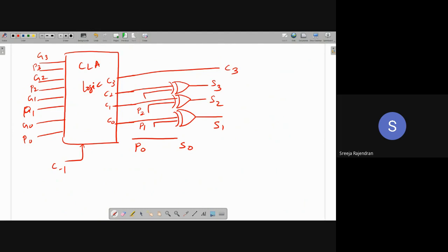Basic gate. Now how do I construct the gate? I have different technologies I can use. I can use MOSFETs, in which case it is CMOS technology. We have not mentioned technology so far. Then there is ECL logic, TTL logic, so different ICs are based on different logics. In the manufacturer sheet itself, the data would be provided as to what the propagation delay is. There are mechanisms to calculate the delay, but for that you have to go to the transistor level representation.